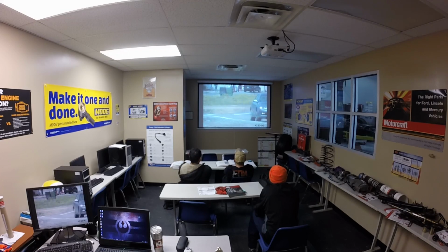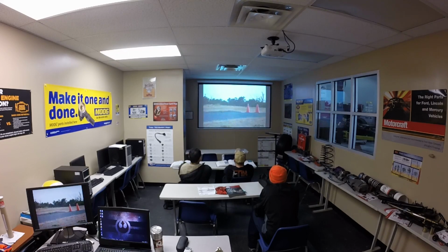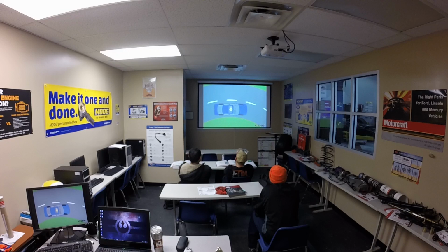Acceleration puts more weight on the rear wheels. Deceleration or braking has the opposite effect. In a turn, centrifugal force tries to push the vehicle away from the corner. This is resisted by the cornering force of the tires. The tires have slip angles due to the cornering forces acting on them, and since the cornering forces at front and rear may not be equal, the slip angles at front and rear can be different too.